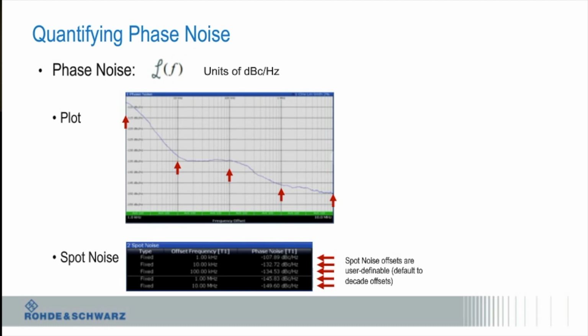Okay, so if you look at phase noise, this is actually a fairly typical plot of a PLL type oscillator. You'll see here there's some slope. This is really inside the loop bandwidth of the PLL, so it has to do with the loop filter. Then there's some divider noise, etc., VCO noise.